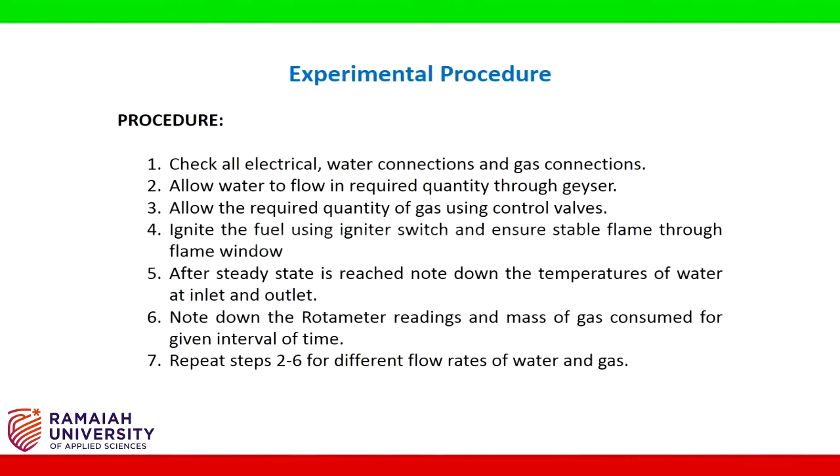5. After steady state is reached, note down the temperatures of water at inlet and outlet. 6. Note down the rotameter readings and mass of gas consumed for given interval of time. 7. Repeat steps 2 to 6 for different flow rates of water and gas.